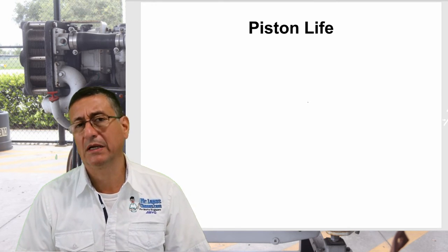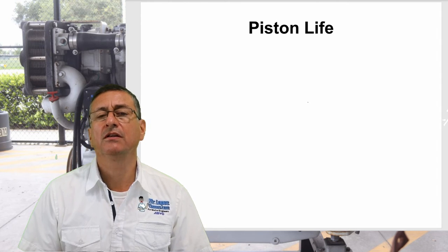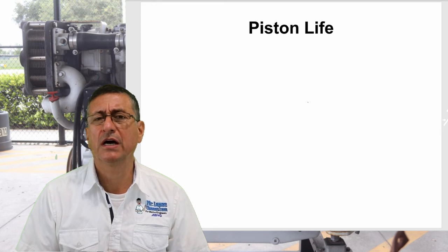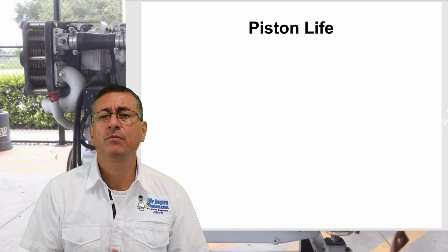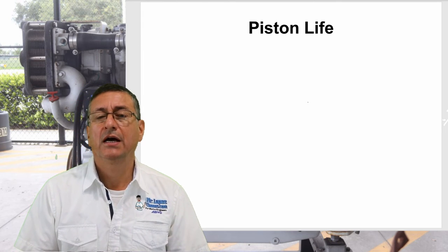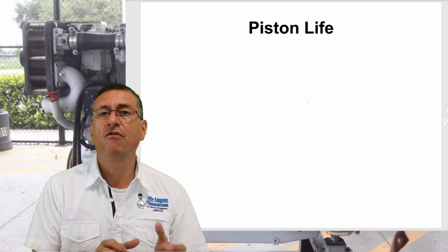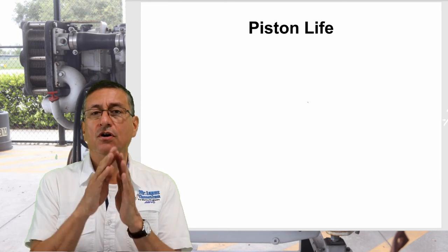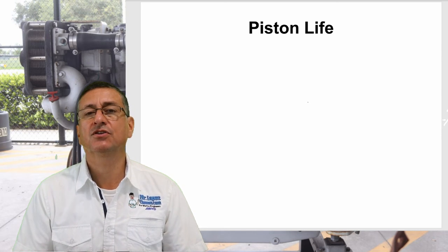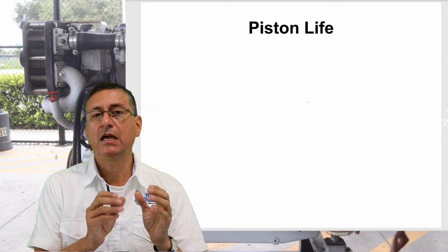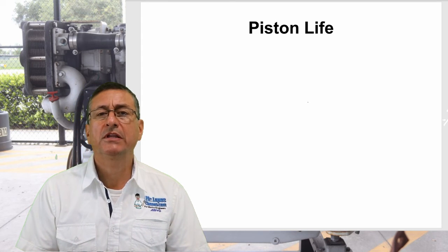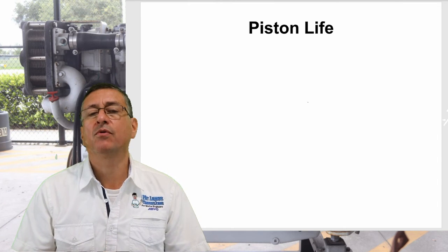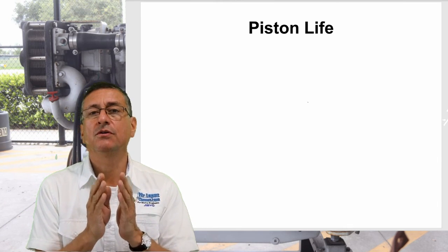What happens with those materials? What are the materials recommended for the fabrication of pistons? If you remember, in previous episodes I explained the difference between cast aluminum and forged aluminum, and the difference between cast iron and forged iron. The main difference is the organization of the structure between cast material and forged material. The forged material is forged in special hydraulic equipment, and organizes the structure better.